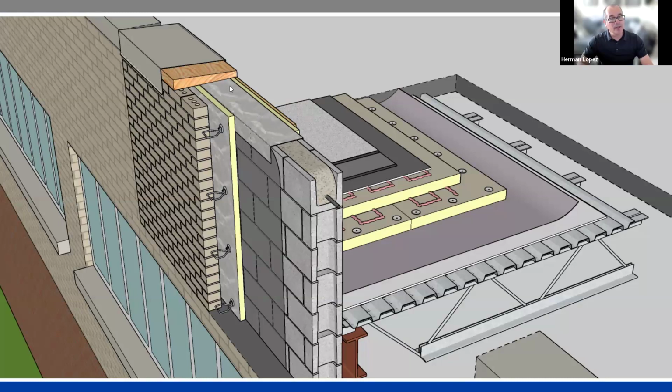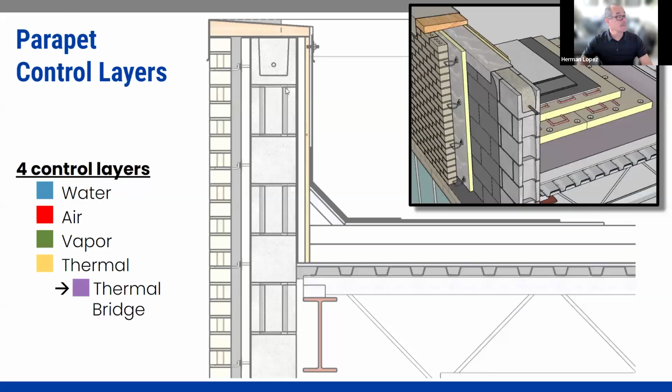And so, Ben, it startles me how often I see somebody throw a fastener or two through the top of that cap flashing, and it breaks your heart because now we've got a breach in that protection that we were looking at. All right, so let's go to the cutaway. Then we'll look at air and water.